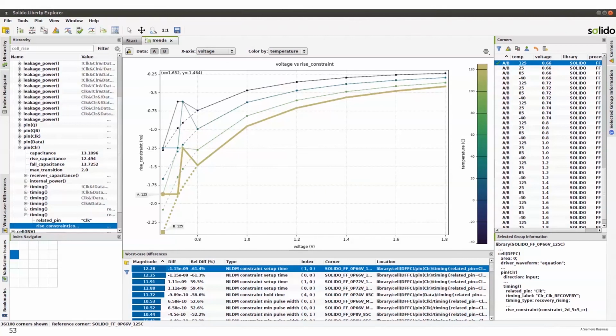So what we're showing is statistical margins. The other thing we show is that sometimes, if you're taking the worst case PVT condition, for example, and just trying to show statistical margins there, you might actually be missing what's really the worst, because what's worse at nominal is often not the worst case at statistical, because you'll get these long tails that happen at some conditions.